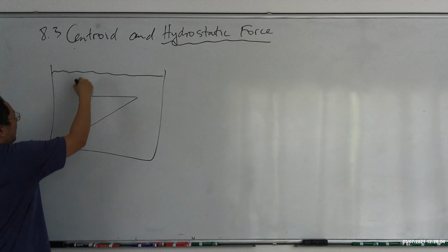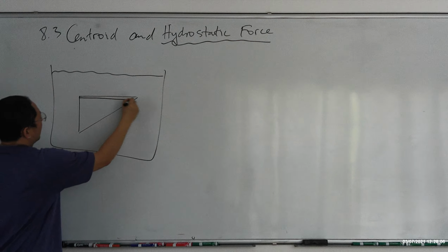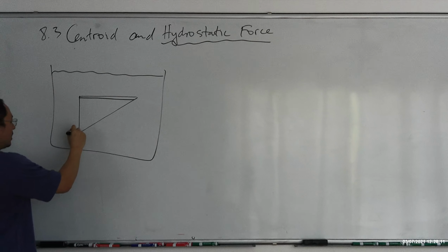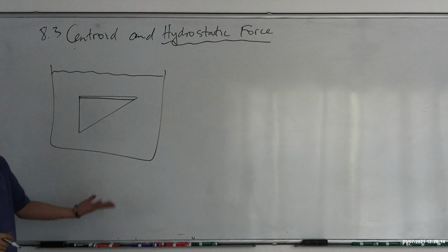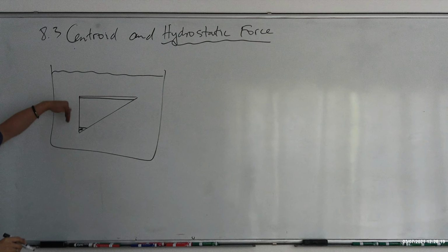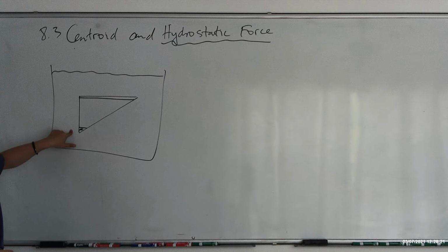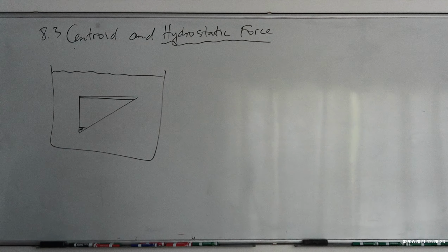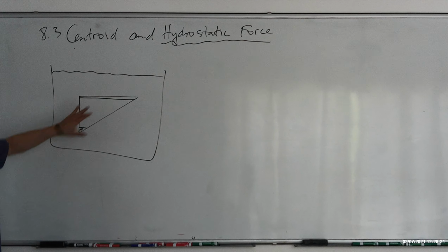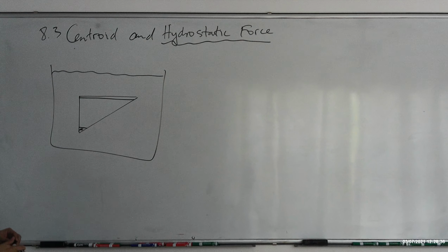And you see, if the region is closer to the surface of the water right here, then the force is going to be less. The pressure is going to be less. Okay, pressure is force over area. And then if the point right here is lower, deeper into the water, then we're going to feel that the force in there is going to be stronger. Okay, so the question is, how much total force is applied to that plate, let's say metal, but who cares, anything that we immerse into the liquid.